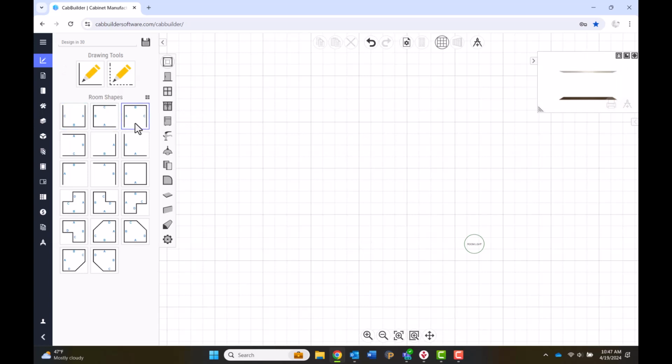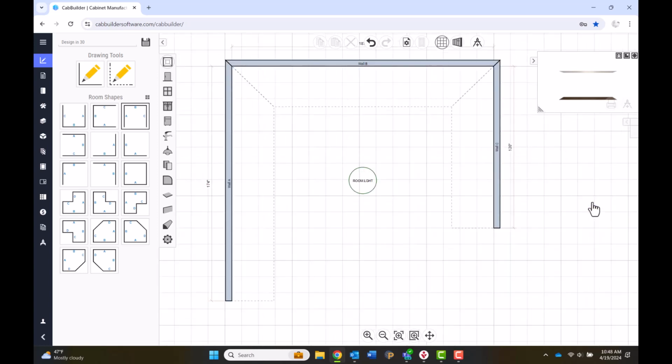the process. Click the desired room shape, which will activate the Attributes box so that you may enter the appropriate wall lengths, wall height, and wall thickness. Enter the appropriate wall length for each labeled segment. Once the desired values have been entered, click the Apply button to automatically draw the walls.